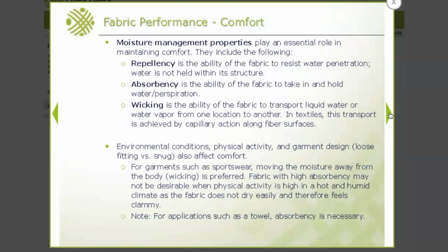And then we have comfort. Comfort properties are moisture management, for example. You know, how absorbent is your fabric to moisture? Absorbency is very important for comfort because when you are wearing a t-shirt, for example, and you're sweating, you don't want that sweat to just stay there and stick to your body and make you wet and clammy. You want your t-shirt to take that moisture away from your body and make you feel dry. And so fabrics that are absorbent, or have good moisture absorption, will feel more comfortable. Like cotton will be more comfortable in the summer because it absorbs all the moisture from your body.